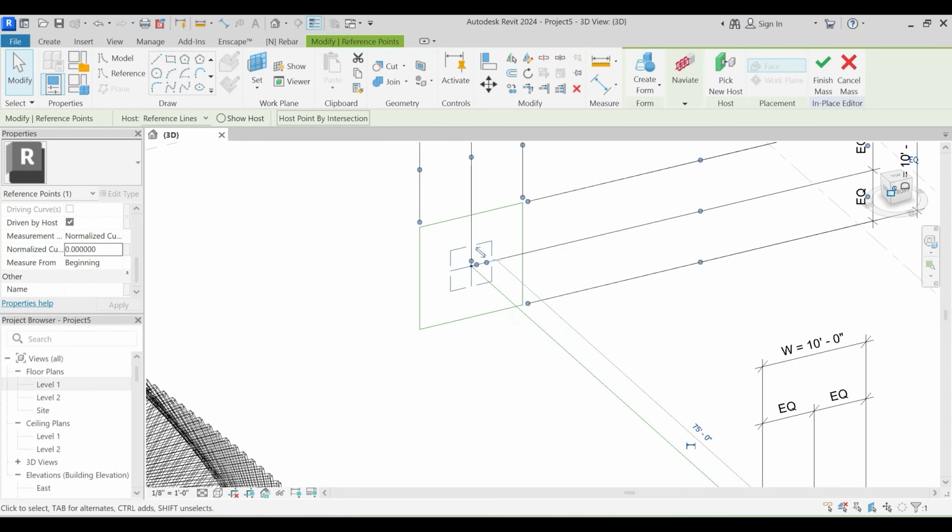Yes. And why is it not selecting the individual surfaces? You need to press Tab a couple of times. Press divide surface, select that, and say 25, 30, 25, and 60. Okay. Same for this. Press Tab a couple of times until you find this surface, divide surface, and say that 25 and 30, 25 and 60.